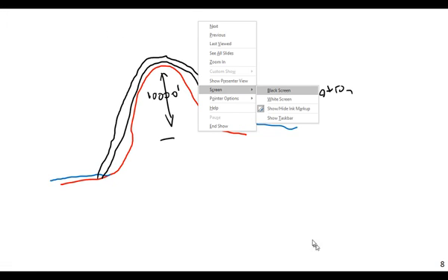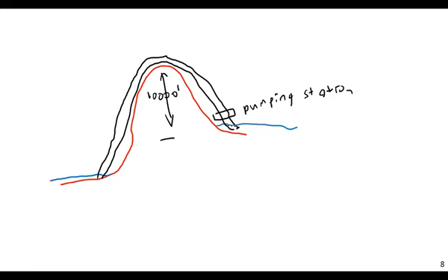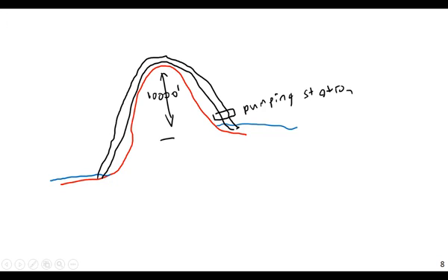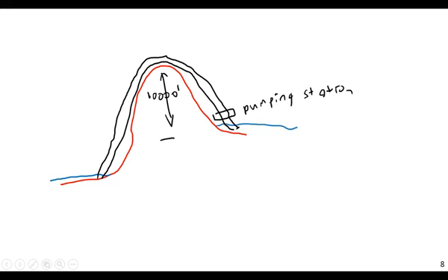And this reservoir here will continually drain into the lower reservoir based off of siphon action alone. So you would have to use pumps, but only to get the initial thing going. And you have to rely on pumps at the bottom to push water up the hill, rather than relying on a pump up here to initially pull water up the hill.